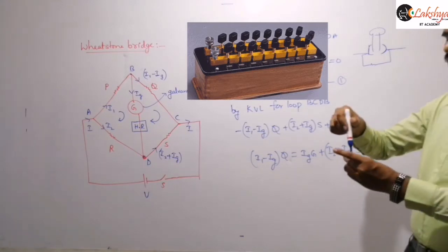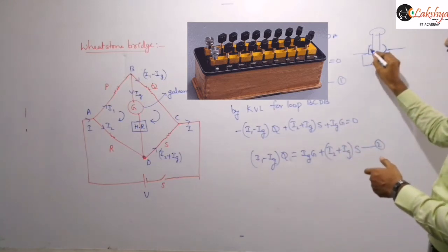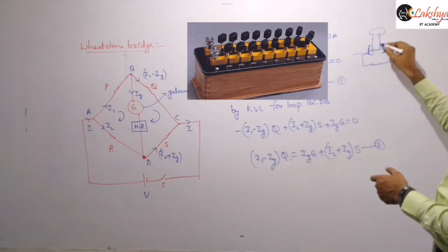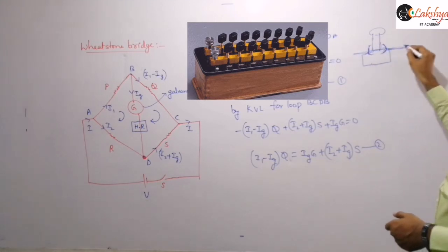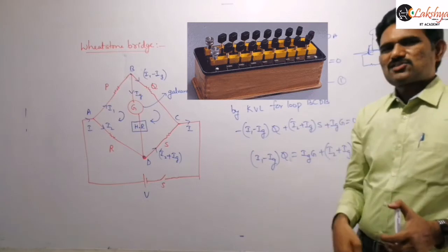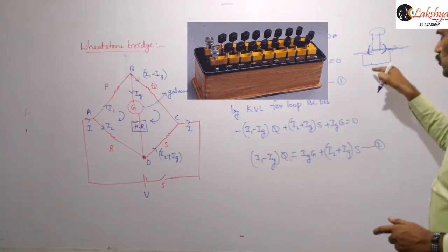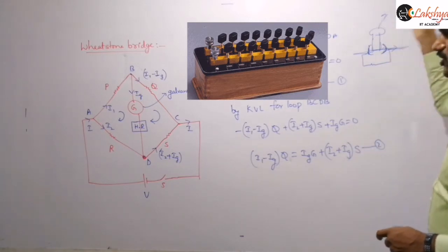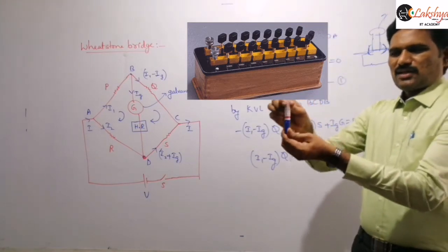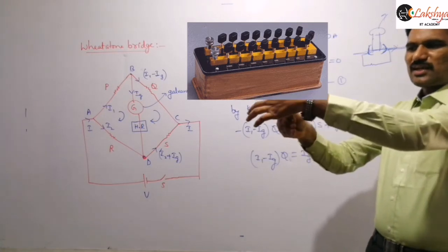So if you are putting that plug here, that indicates that now this is a conducting path, then current will flow directly from one point to the other point like this, because this plug makes contact with this. So directly current will flow like this. When you are removing that plug, that means if you want to short circuit that high resistance, we need to keep that plug, we need to close that plug. If you want to include this resistance, we remove this. If you pull it out, just pull it out like this. If you are putting it like this, then it will make contact with the walls here. Then it will be short circuited. Current directly flows here.